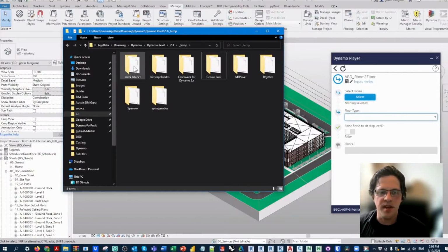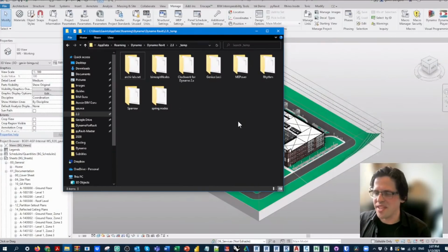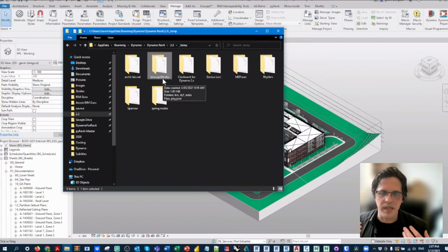Awesome. I'm finding I use Archilab a little bit less these days. It's a silly reason, but there's this tool in there called the automatic relay tool, and if you double click a wire, it creates a little relay in the middle, and if you delete it and you click off, it crashes Dynamo, and it's so easy to make these things. If that wasn't in there, I'd use Archilab more, but Bimorph nodes is great for working with linked files and doing some intersections really quickly.